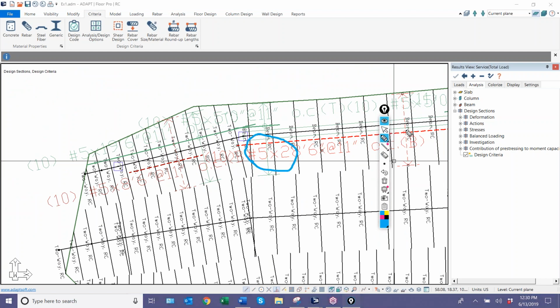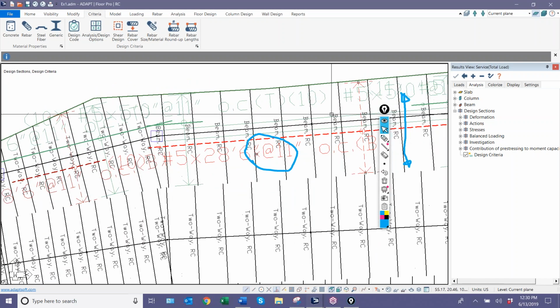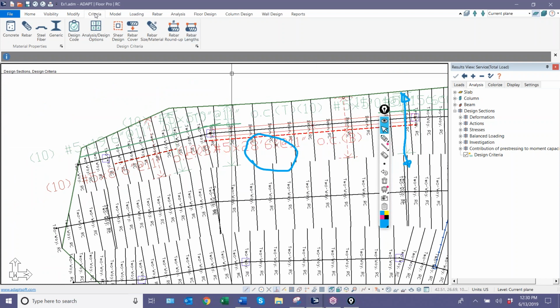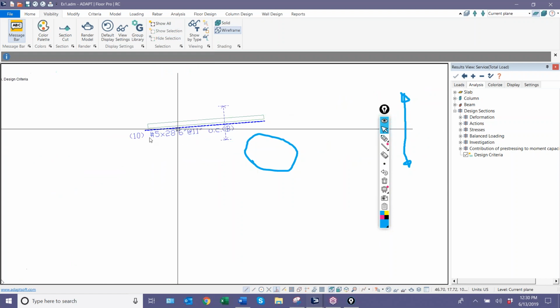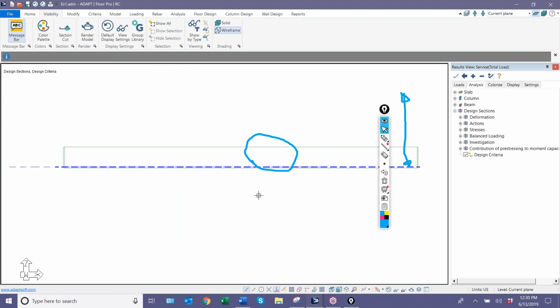And it's hard-coded to show the bars based on the designation of the support line also, which is a two-way slab. That's why the bottom bars are actually shown distributed, like so. And so if I look at this in elevation, let me select the beam first, bottom bar, and under visibility, I'll go ahead and show that one set of components, and I'll turn it on its side just to see what's going on here.